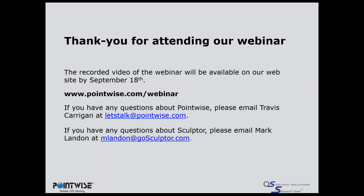Okay, if a large shape change is applied, is there a risk for poor quality elements to be created as part of that deformation? Well, certainly you can do things that would make things unphysical, like turn things inside out and make negative cells. But you want to put some realistic controls on the range of the variables, the mins and the maxes of how far you can move these control points.